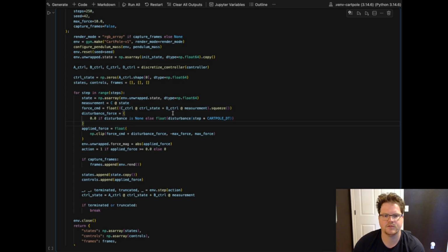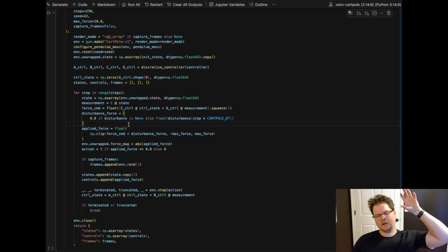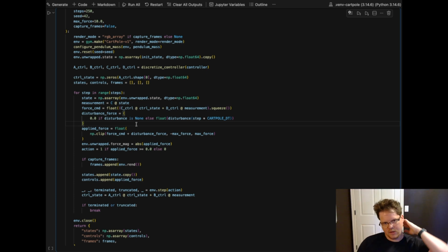So the feed through is that compensator operating on the measurement, and then we have the C operating on the control state, and that's again in our dynamic compensator frame, not just a vanilla C. We packed it into a nice dynamic controller compensator, and so that's what that C and D is at this moment.